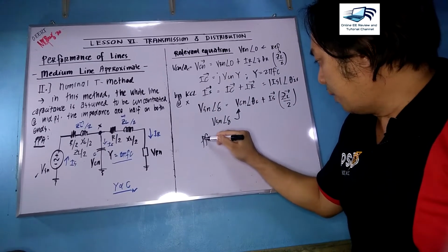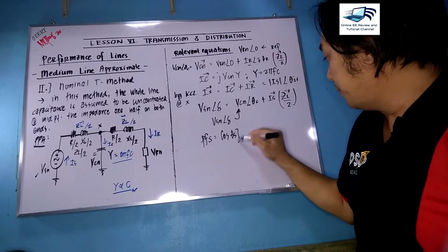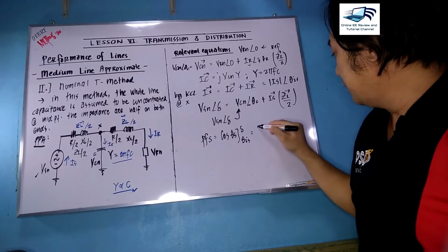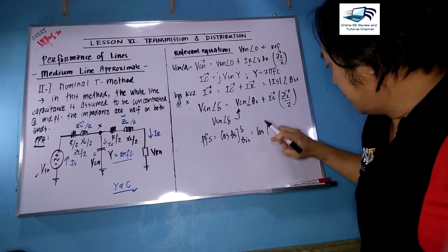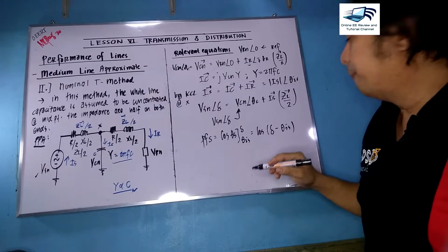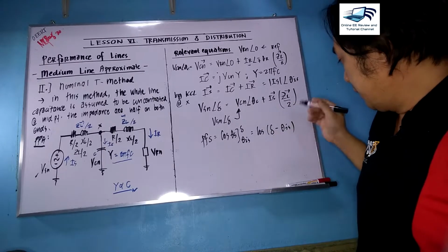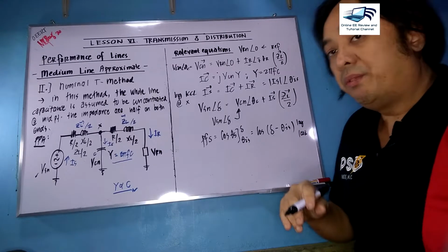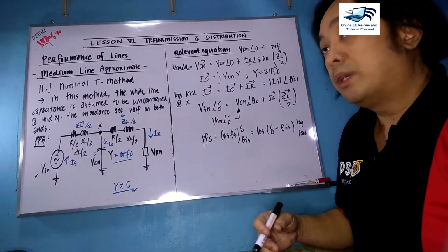Now you can get the power factor at the sending end by having the cosine of theta S, which is dependent on alpha and theta IS. So definitely theta S is theta V, or your alpha, minus whatever your theta IS is here. And if you want to consider, it can be a lagging or a leading power factor, so it will depend on the phasor diagram.